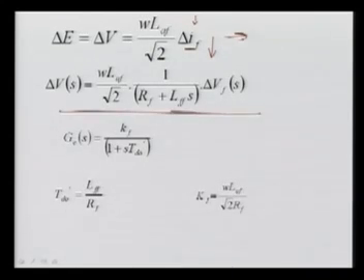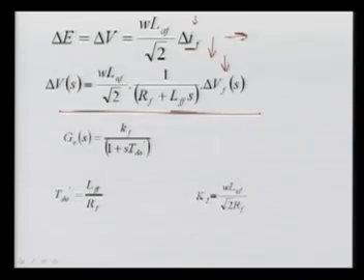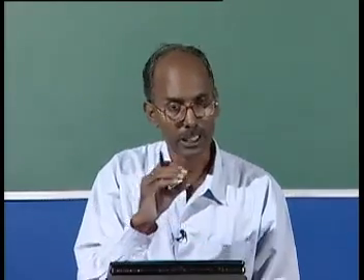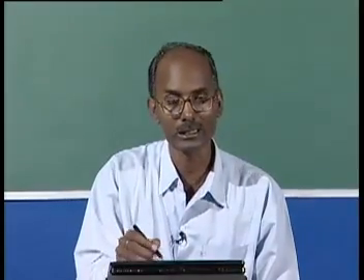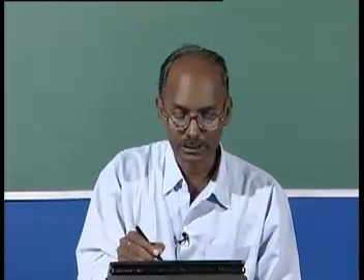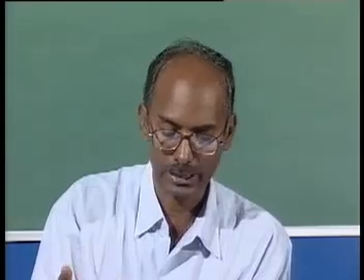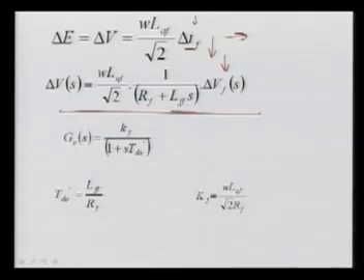It relates the voltage of the field, which is coming from the exciter, the armature being a rectifier, and this voltage is coming as DC to the field winding. So this is a change in the voltage, and we are writing in the difference form to see the behavior of the system. Now, Rf is multiplied here, so we can divide by Rf, and then Rf will go to the other side.